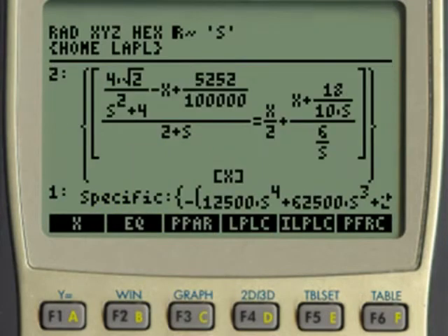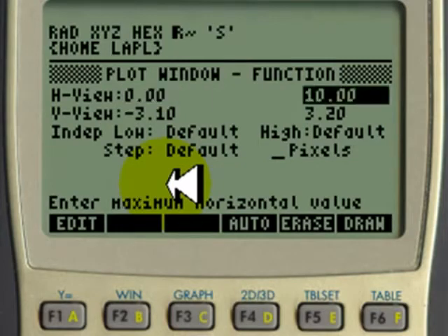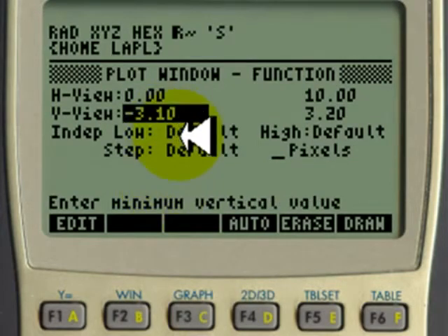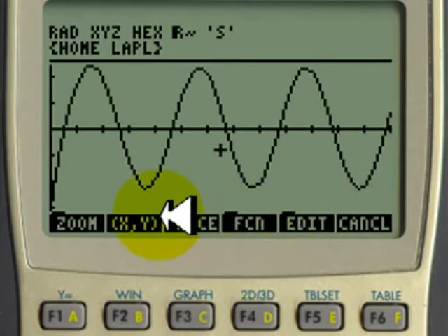And now we go to Shift Windows and say I want to plot that between 0 and, I don't know, 10 is good. And what is the vertical axis? We'll make a computation there. Good. Erase what you have and draw a new plot. That is the voltage in the capacitor. It begins at negative 1.8 volts and then it moves to a different oscillation, the new steady state.